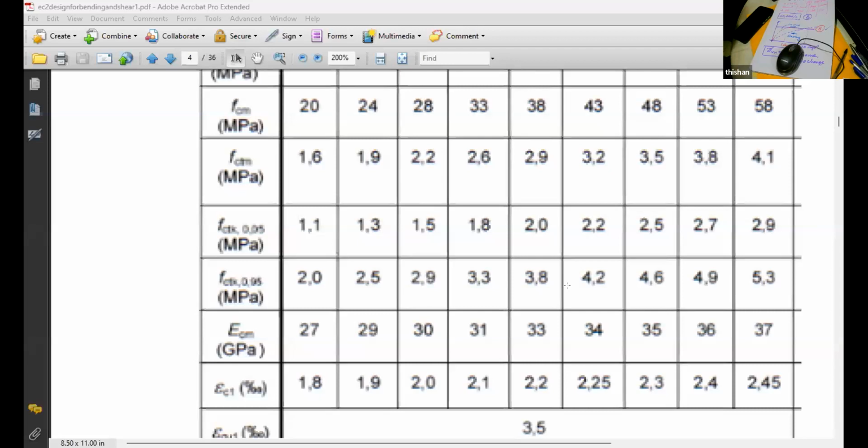And you need very good dynamic behavior with respect to wind-induced accelerations at the beginning of the project. By the time you sell your apartments, if the building is stiffer, it will have a lesser wind-induced acceleration, and you'll find people are happier, because your calculation was more based on 1 year return period.